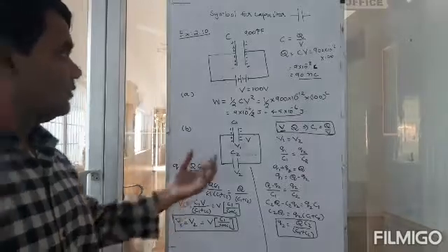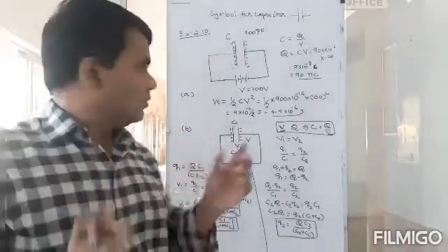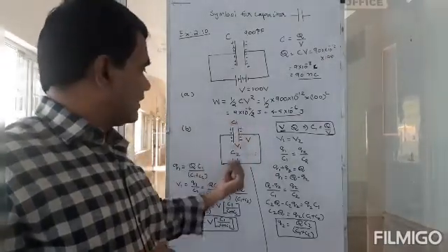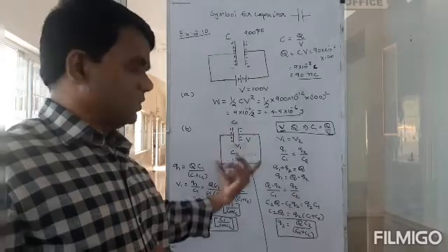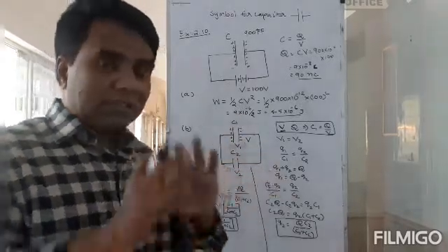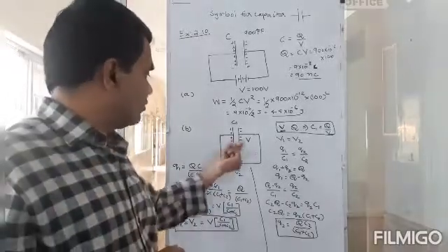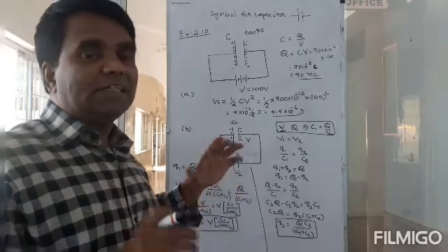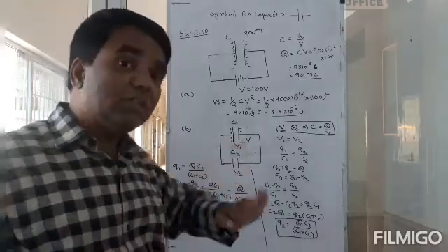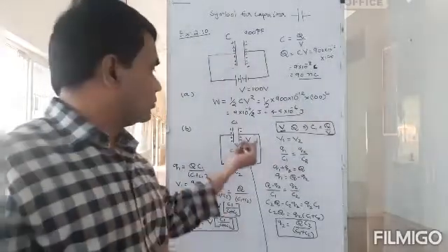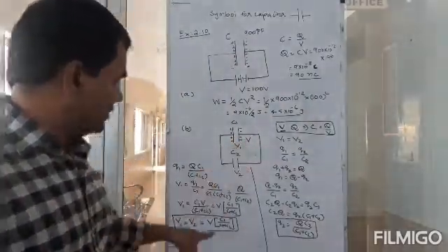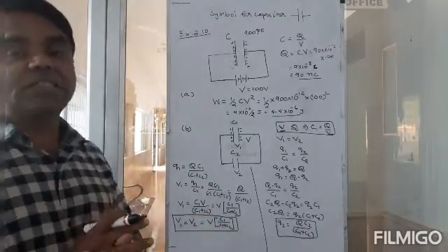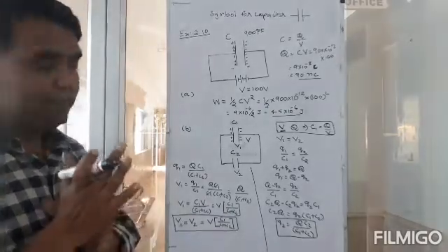So what have we done here? We've taken a capacitor which was charged to voltage V, the capacitor value is C1, and I am connecting another capacitor C2 across this. The charges will flow and then they will reach an equilibrium where this voltage will be equal to this voltage. When this voltage is equal to this voltage, what would be the relationship between the final voltage and the initial voltage with which we started, which was V, right? So V1 is equal to V2 is equal to V into C1 divided by (C1 plus C2). Okay.